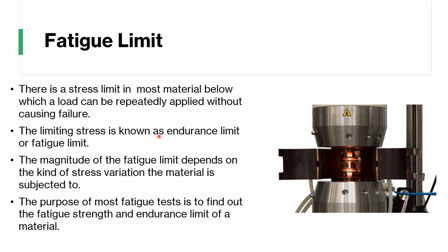The limiting stress is known as the endurance limit or fatigue limit, something the material can tolerate. The magnitude of the fatigue limit depends on the kind of stress variation the material is subjected to. The purpose of most fatigue tests is to find out the fatigue strength and endurance limit of a material. We do testing to find that limit, how much the material can stand.